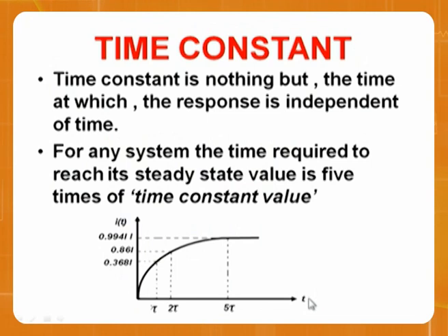It may go up and stay there, it may go to 0 and stay there. At a higher value it stays there, steady state; at a lower value it becomes steady state. So it will almost reach the steady state. That's why the time constant is defined in terms of the value called 5 tau. So this is current, this is the time axis.